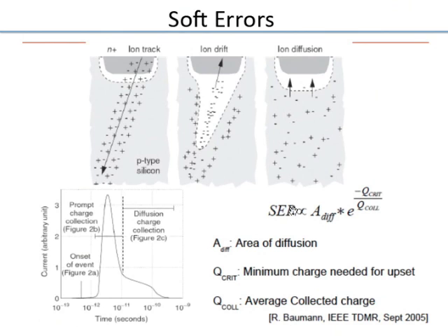It's called a soft error, and the rate of error depends on the area of the diffusion. If you have large diffusion, you have more charge created, so there is more chance for error. Of course, you want large diffusion if you are doing a detector for these ions, maybe for these colliders and so on, or maybe a detector to catch light, like CMOS image sensors. So you want large areas there, but otherwise you want to keep these areas small.